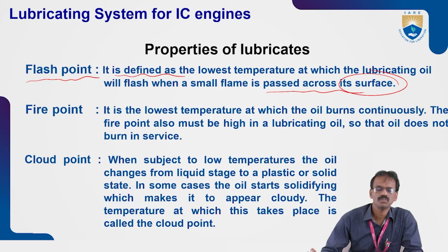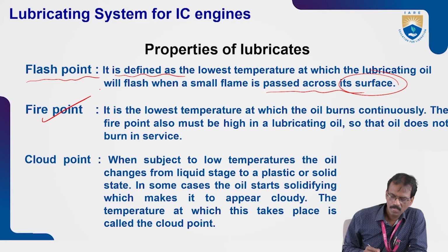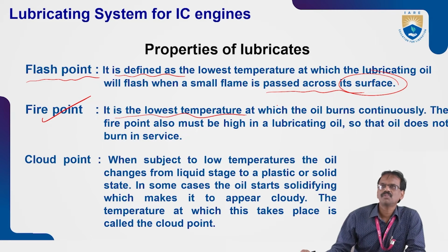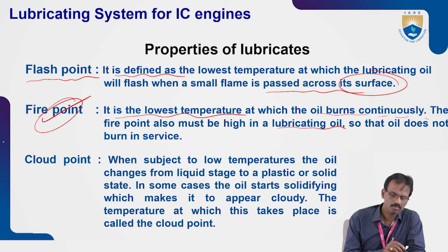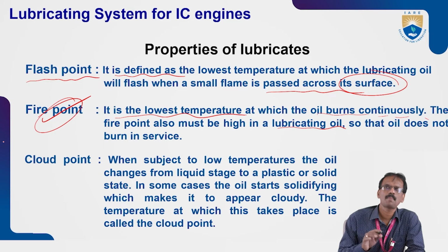Next, fire point. It is the lowest temperature at which oil burns continuously. The fire point must also be high in lubricating oil so that the oil does not burn on surfaces, because the lubricant should withstand a certain temperature.